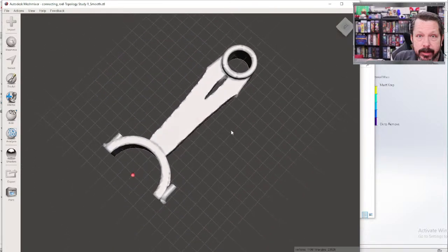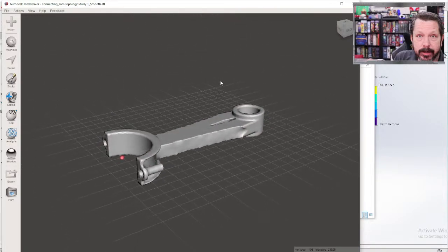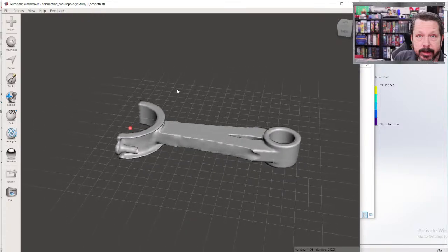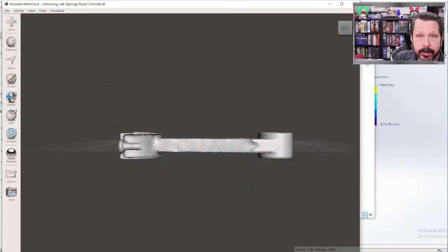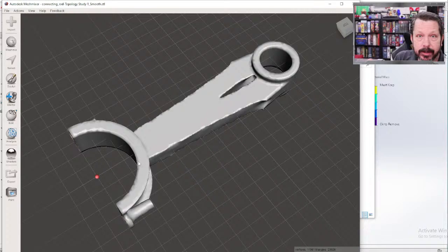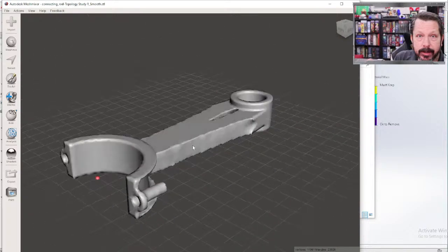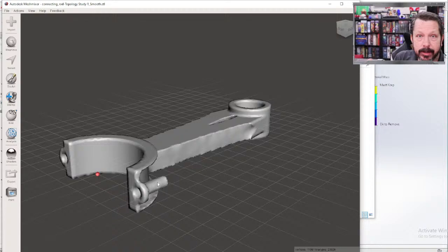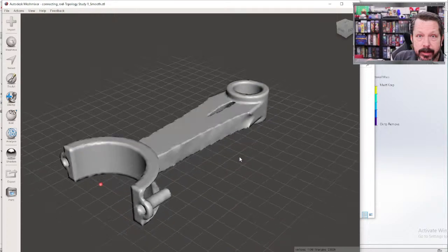So what you would do now, as the engineer, is go in and make some decisions like this little indentation here, probably not good, because we put the constraint that this surface was held still, but we're probably missing a good number of forces. For one, the clamping force in this bolt hole, that's definitely not the bolt hole I would want to have holding the end cap on the connecting rod.